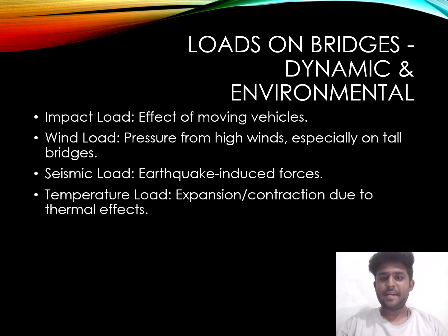Loads on bridges, which are dynamic and environmental. Impact load, effect of moving vehicles. Wind load, pressure from high winds, especially on tall bridges. Seismic load, earthquake-induced forces. Temperature load, expansion and contraction due to thermal effects.